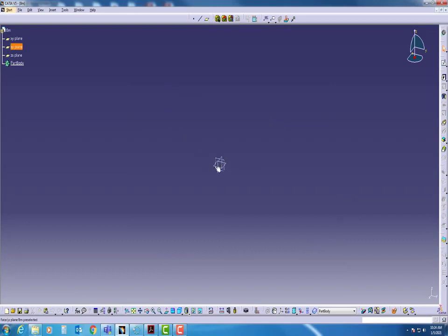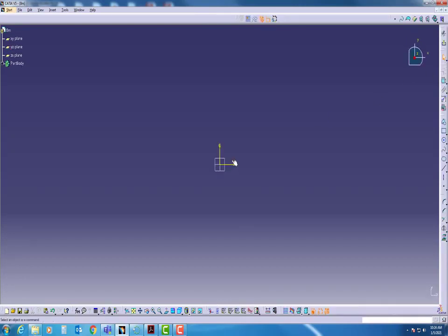Down here we have a lot of our planes. You'll notice in the top left that it signifies which plane is which. I want to use my XY plane, that way left and right is X, and up and down is Y. So I'll click that, and with it highlighted, I'm going to come up to Sketch. What that does is orient me to the X and Y.